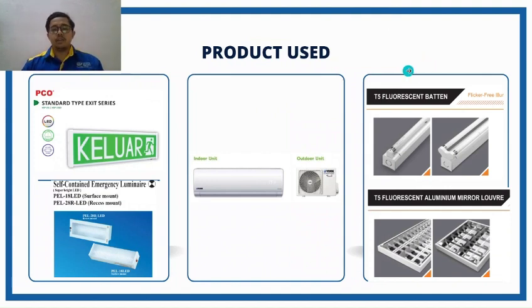What I learned from this project is that we need to carefully calculate the space for lamps, sockets and aircon. We need to measure it right and precisely, because it will affect how many lamps, sockets and aircon are used in the room. For assignment 1, I made a mistake and it troubled me a lot, because I made a mistake in the area calculation and forgot the emergency light.